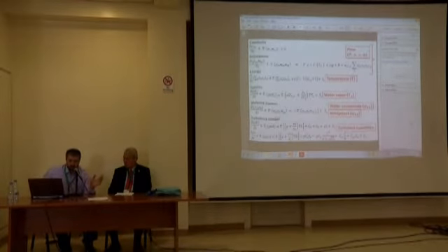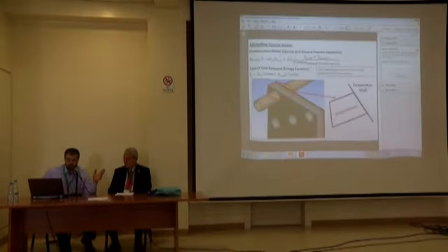For those who would like to know which equations we are solving inside Fluent, a commercial CFD code: we are using the mixture model for the multi-phase. We have one continuity and three momentum equations for the flow, temperature by the energy equation, water vapor predicted by the species equation, and two volume fraction equations for the water condensate and the refrigerant. And of course, due to turbulence effects, we account for them through a turbulence model. We're using the realizable k-epsilon model.